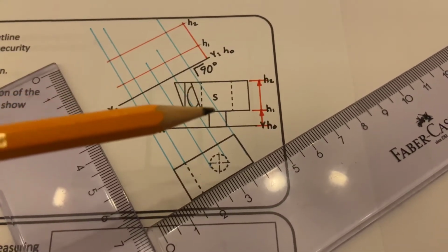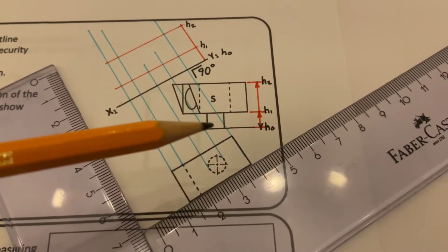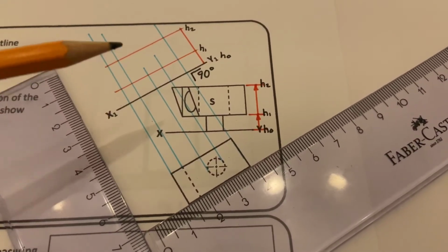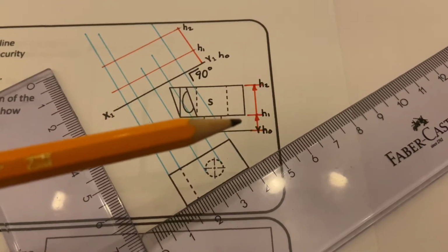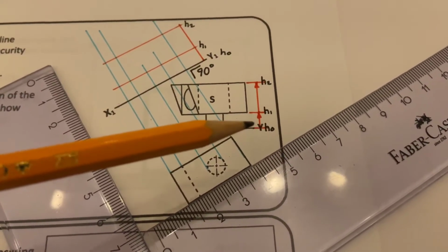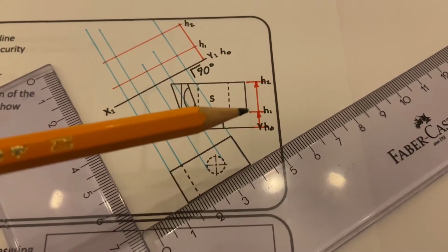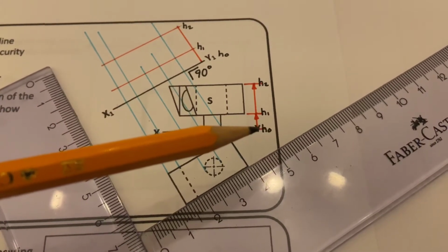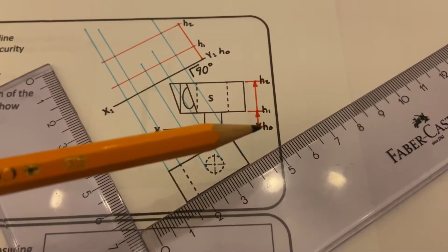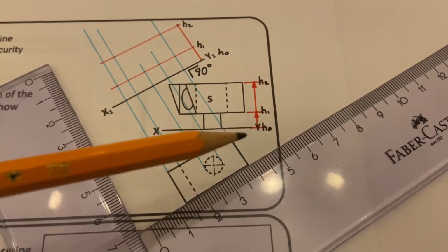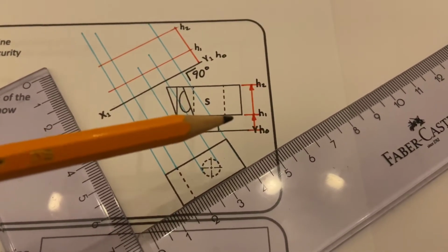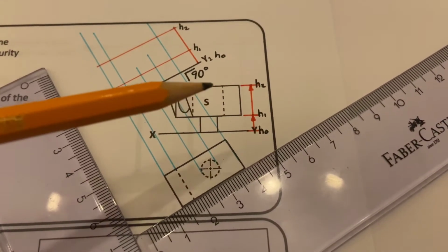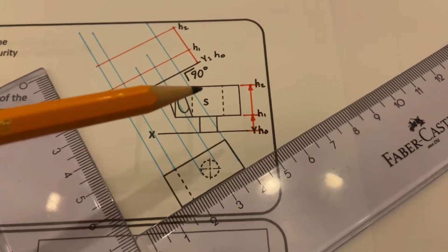Heights do not change from one elevation to another. So whatever the height of the points are in this elevation, they must be the same height in this elevation here. So over here I have drawn a height line, and I have marked up H1 and H2 and the ground then H0. So there are three heights that we have to consider. H0, which is the ground, H1, which is where all these points are, and then H2, which is the ultimate height of the camera.